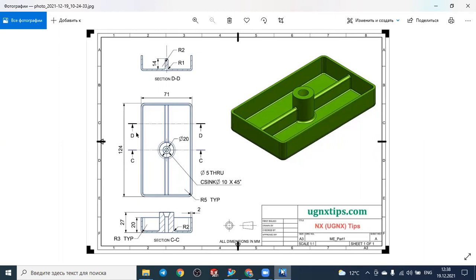At this time you can create this cylindrical element in the middle with here the diameter is the 20 and the smaller diameter is the 10. So here we have the chamfer of the 45 degrees in this side. So let's draw this element here in the middle.